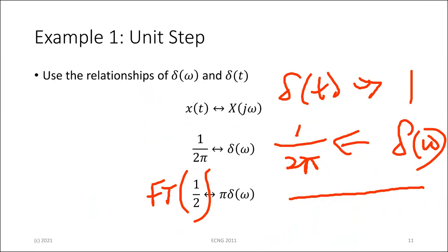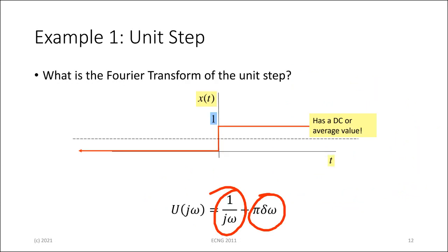What would an impulse in frequency give me? Intuitively, it should give me a constant in time. And we just worked out exactly what that constant in time was, and it turned out to be 1 over 2 pi. So you have that dual behavior coming in. Once you understand that, the rest kind of falls into place.